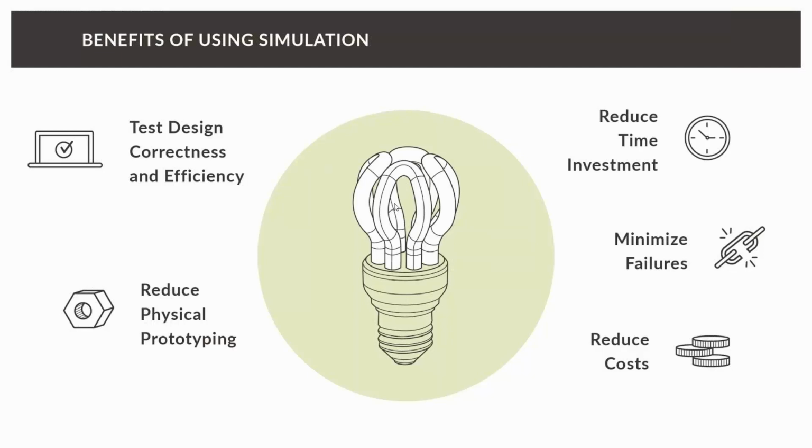Later we'll also talk about the time investment for preparing such an EGR valve simulation. But usually, if you're an experienced user, the typical turnaround time is around 24 hours. And in these 24 hours, you can compare and simulate as many design variants as you want in parallel. This helps us because it allows us to find failures at the very early product design stages, where we can test different concepts, and therefore it gives us much more flexibility. And at the end of the day, this helps us to reduce our costs.